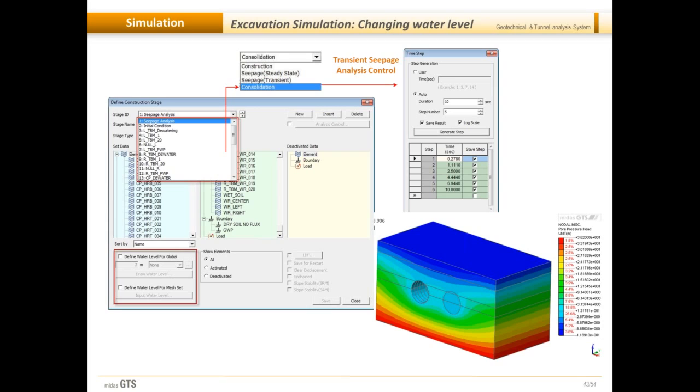So if the excavation is taking place in low permeability clay soil, then rapid construction process may result in no volume change at all. And that is, we are doing excavation in undrained ground condition. But in clay soil, what happens is after the tunnel has been constructed and the lining is installed, the ground displacements are likely to be seen to continue at the surface.